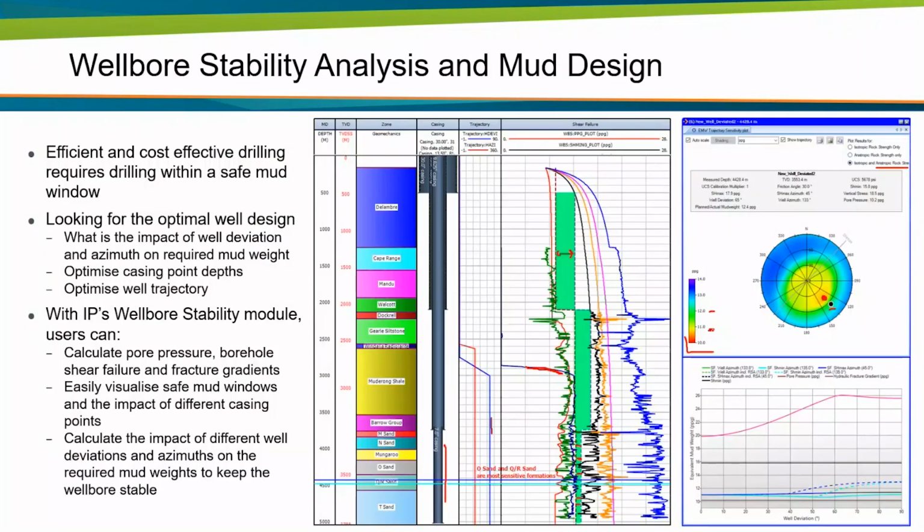Where is the uncertainty coming in all of this? Let's say here we have a calculation. It has one rock strength. It has one maximum horizontal stress. What if there is uncertainty in your rock strength? What if my rock strength is plus minus 10% or plus minus 20%? Or what if I have three different models, a low, mid, and a high case? How can I account for that uncertainty? Well, you can account for that by Monte Carlo analysis.